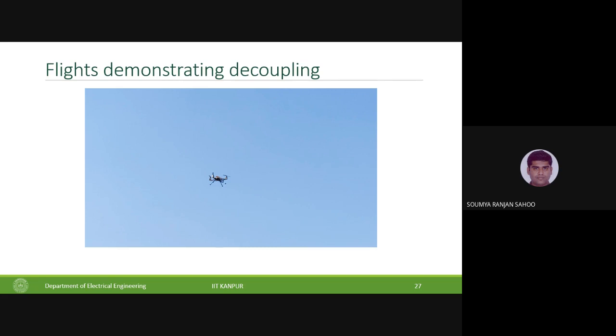For that, we first investigated, can we do it with a fully actuated setup? It turned out that it is not possible, and then we moved on to over-actuation. Over-actuation essentially means the servos are not coupled. So we have 4 independent servos, which means 4 independent rotor tilt angles, and of course 4 independent rotor speeds. The 2 videos that I am going to show you are going to demonstrate a position hold.